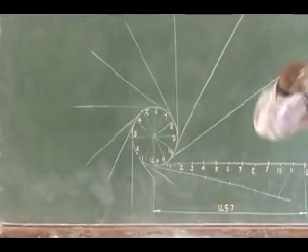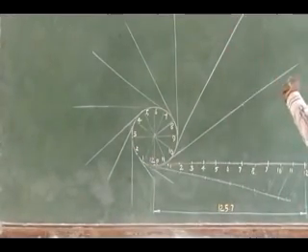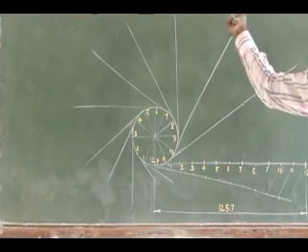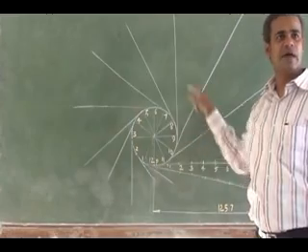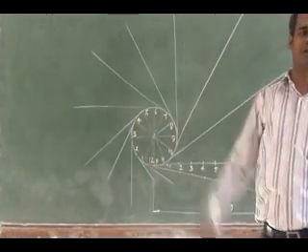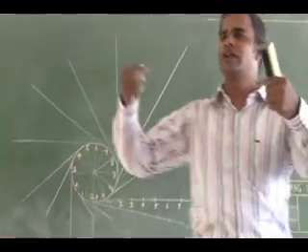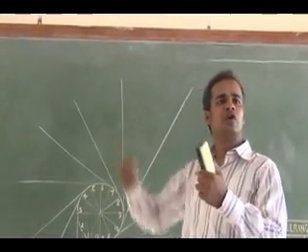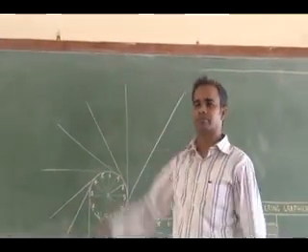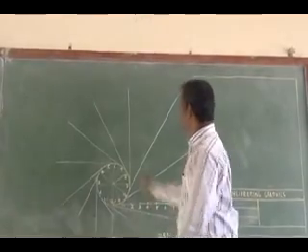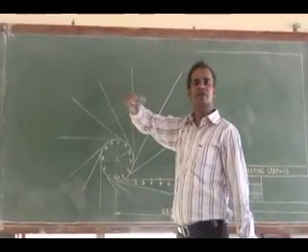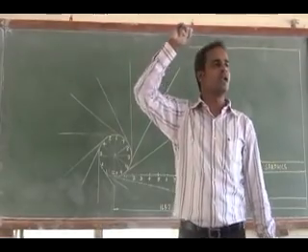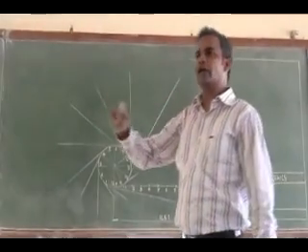The radius of this involute for a circle will be varying from point to point, continuously, because the circle is again a polygon, an infinite polygon. So I cannot use my compass to draw the 12 segments. It will be drawn freehand.